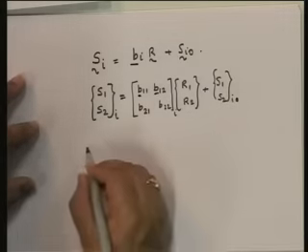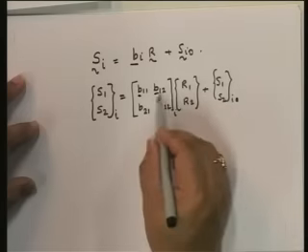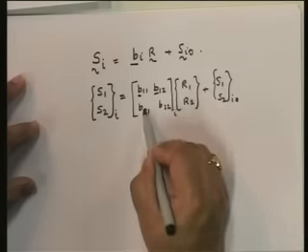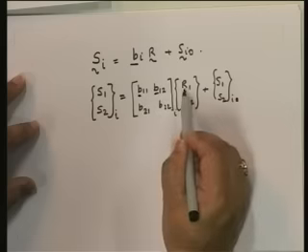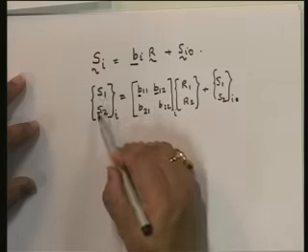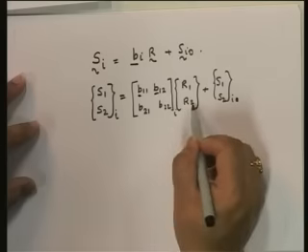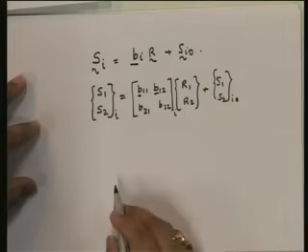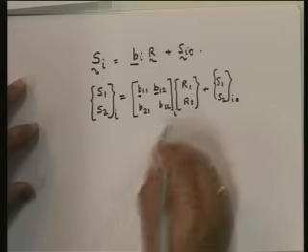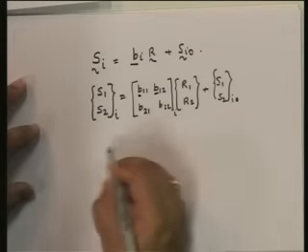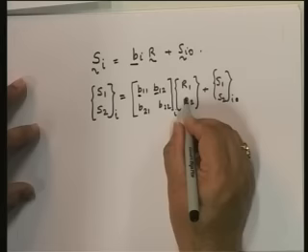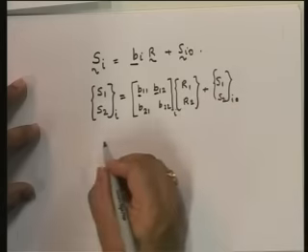In this case, remember we computed this. How did we compute this? We computed this by putting R1 equal to 1 and finding out what the member end moments were, and we found this by putting R2 equal to 1 and finding out what the member end moments are. So in this particular case, understand that R2 is X1.